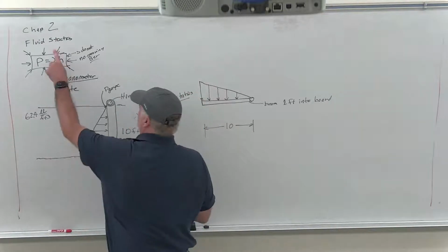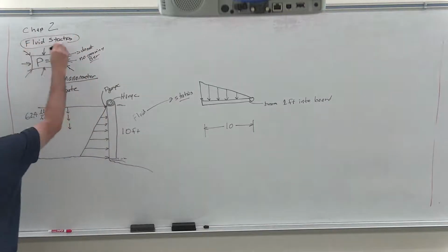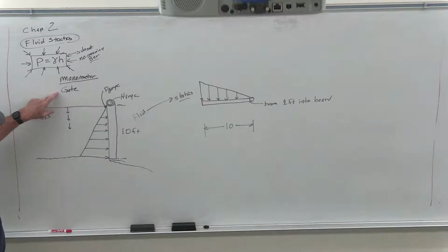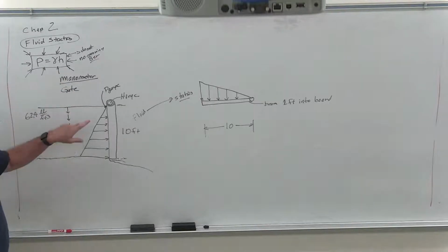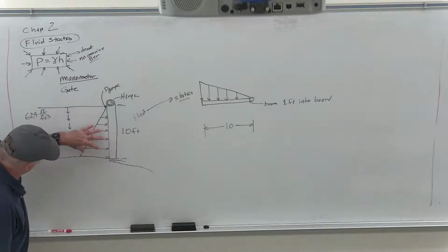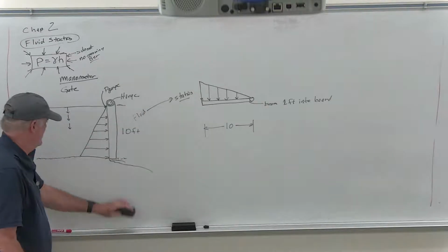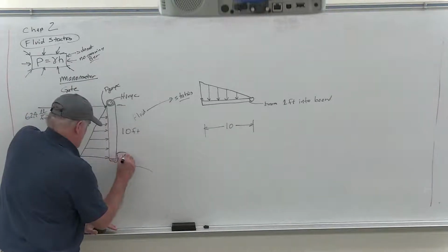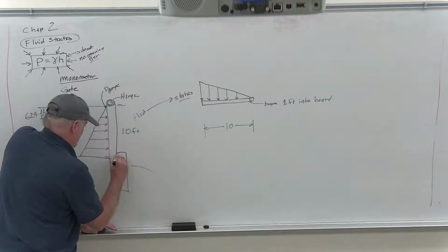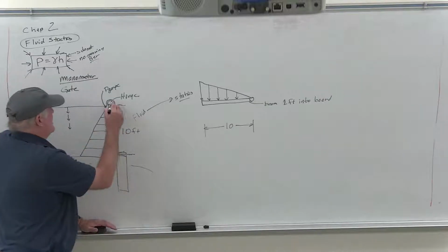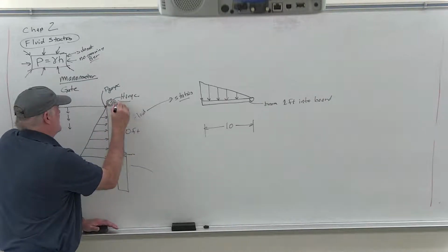And that's why they call this section fluid statics, because after you get past manometers, and when you get into gates, everything you see kind of looks like statics. And it is statics, nothing's moving, it's static. So in essence, to keep this gate from swinging open, somebody has to go back here and bury some big piece of concrete so that the thing is pushing against it. So this concrete is pushing against the bottom of the gate, and hopefully the hinge is holding it, so it's going to be holding it that way too.